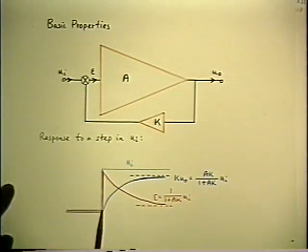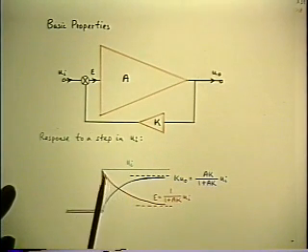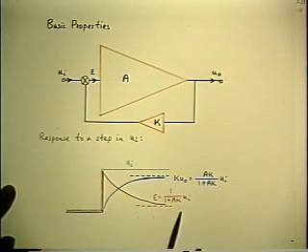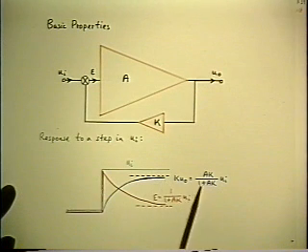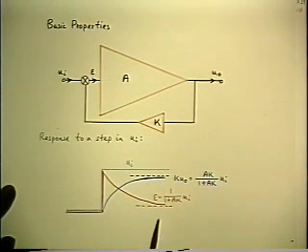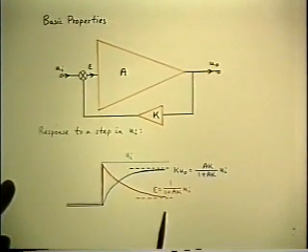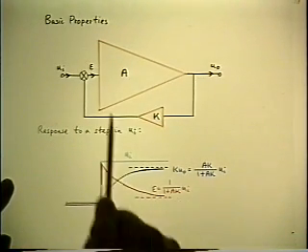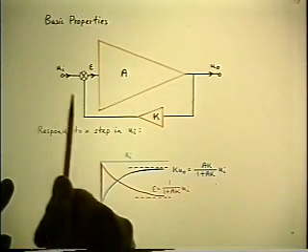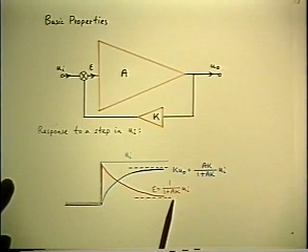So what happens is, as the output rises, it subtracts more and more from the error signal, and the rate of decrease of the error signal gets less, and the rate of rise of the output signal gets less as it approaches the steady state simultaneous solution of the two equations. And the final steady state is not zero error signal, but the value of error signal which, when amplified and fed back and subtracted from the input, gives rise to the same value that it started with.